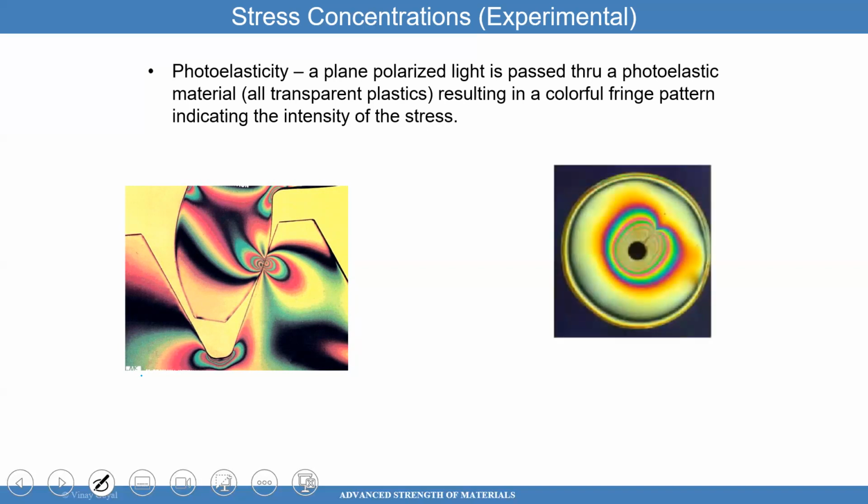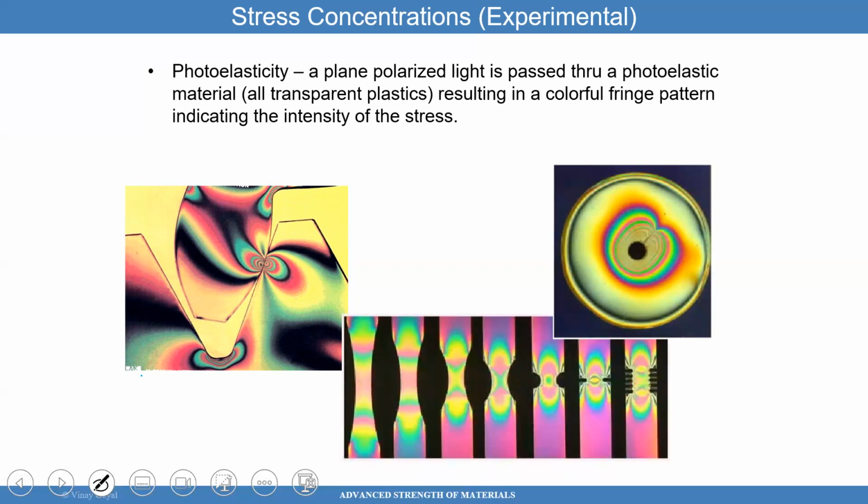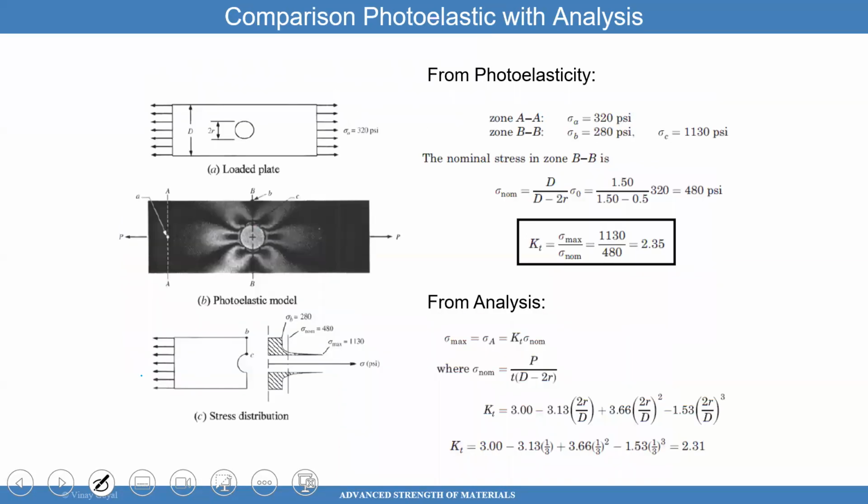And that's another example of photoelasticity being used. These methods have been very successful at showing what the stress fields are and match very well the Airy stress function calculations we showed. Here, what I show is 3 things. Let me go step by step so you understand what these are. Here, the analysis is not an infinite plate under axial load now. Now this is a plate that has finite width.